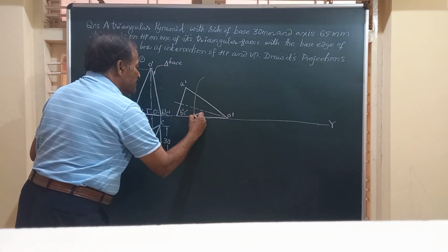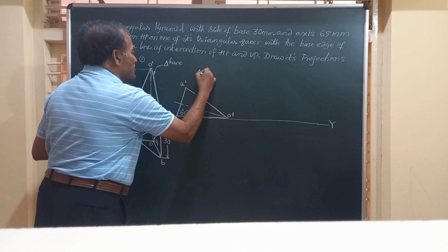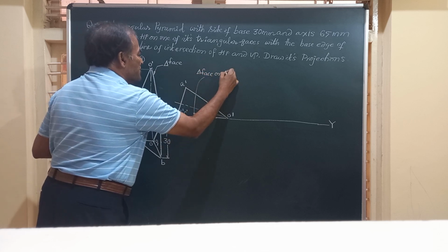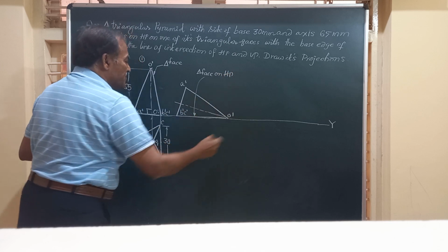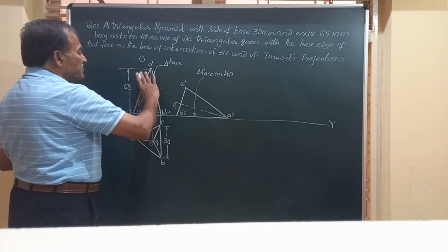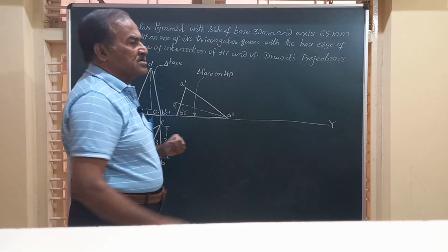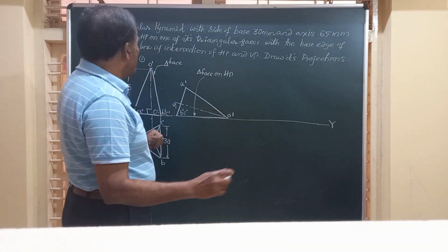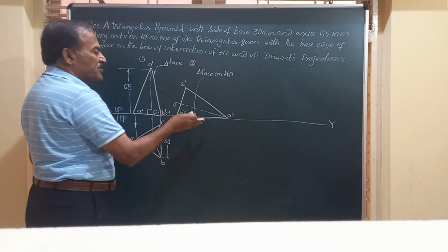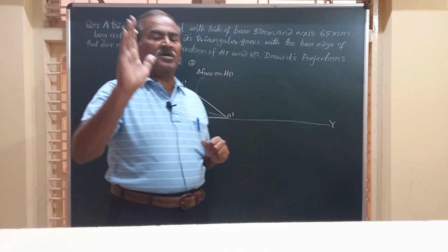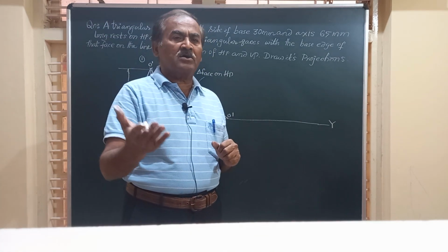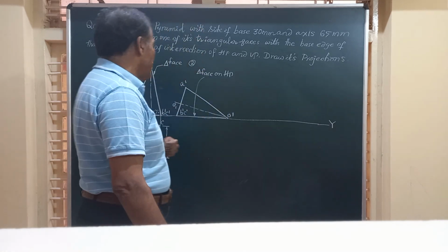I will say here this triangular face is on HP, because the XY line is the HP. Now this is O1 dash. I have written figure number 1 as it is, as figure number 2, and remember friends, figure number 1 and figure number 2 in the front view are always identical, whether it is the case of a lamina or any of these solids for that matter.